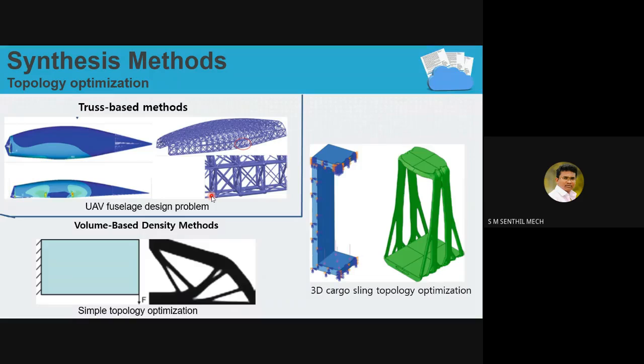There is research going on that you can check. Look at this, one of the results of a finite element analysis from software called ANSYS, which can offer you these results. One region is low and the other is high, so it is good to have more struts at that particular point. In other areas where there isn't any load or stress concentration, you can go for a minimum level of material deposition. This is one of the truss-based methods.